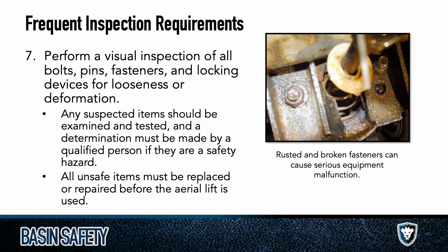All unsafe items must be replaced. Again, it's like before, right? If the instructional markings in the man basket, right, you have your controls up there, are starting to get a little sun faded, but you can still read them. Something to note, maybe you don't need to shut the whole job down, right? Like, it's a little faded there. We probably need to get a new sticker. You don't maybe need to shut the job down. Hydraulics are leaking, right? And you start to go up and you're bouncing around like crazy. Probably time to shut that thing down and take it back to the yard.